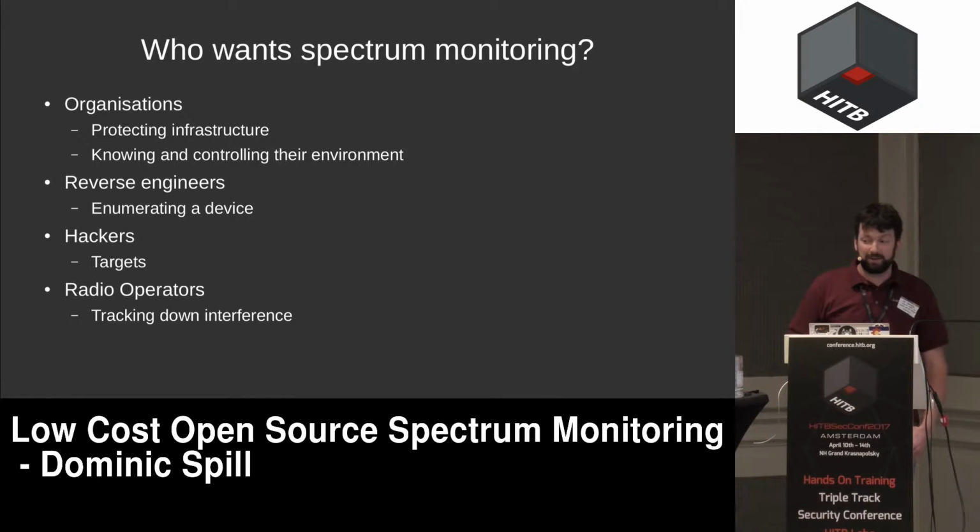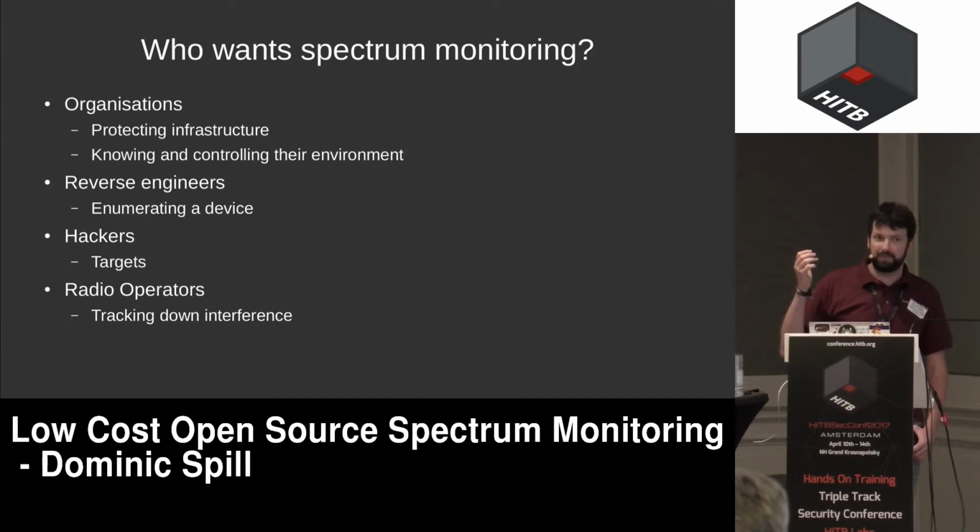But they were baffled by this for a short time before they pulled out a HackRF and started looking at the spectrum and saying, well, it's probably 2.4 gigahertz if they've claimed to be Wi-Fi and Bluetooth. So maybe we look there and we see, and like they were flicking the switch backwards and forwards, and it's definitely something going on. And then Mike Ryan looks at the screen and goes, that looks like Bluetooth. And so then he was able to start decoding it and things like that. But that took the fact that Mike Ryan had the ability to look at the screen and visually identify Bluetooth from an FFT, which is pretty much what I'm going to show you today, that I also have that ability. But hopefully we're moving towards a place where other people have that ability, or automated tools do. And that's really the focus of where we want to get to, starting from this baseline.